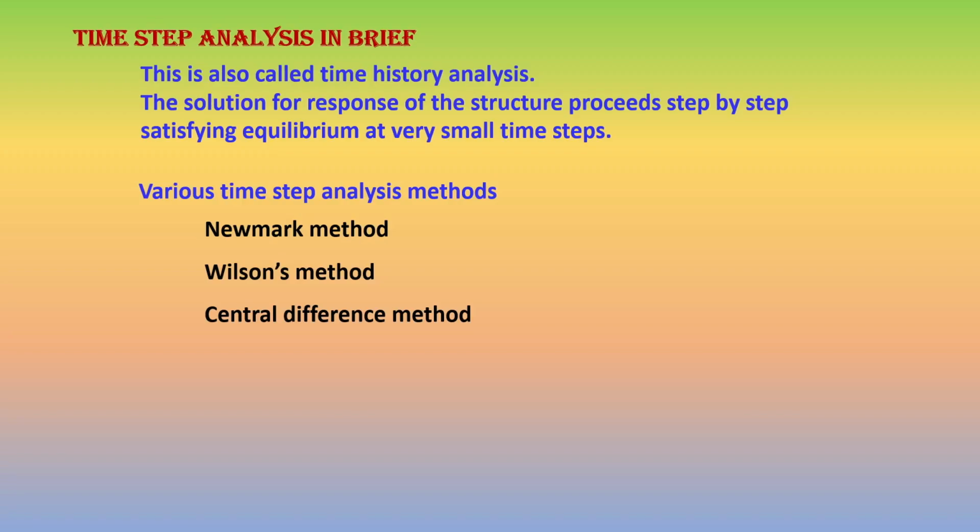In every time step you are getting all the response quantities, not only displacement, velocity, acceleration, but also bending moment, shear force, and all parameters for a structure in the time history analysis. There are many standard methods available for time history analysis, like the Newmark method, Wilson's method, the central difference method, and so on. In the Newmark method also, more internal variations are there, like linear methods, non-linear methods, and so on.